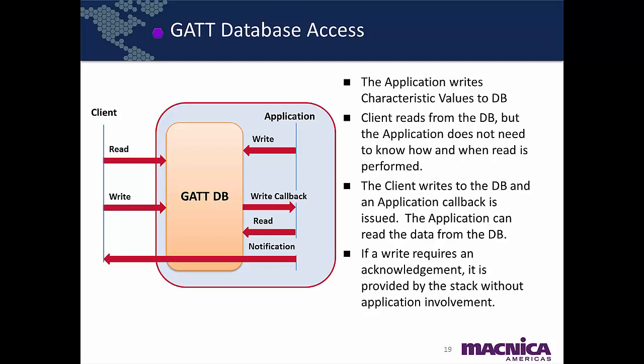At this point, how does the client, let's say a phone application, know that there is a new heart rate value available? Well, a few different methods could be employed. Perhaps the client can be designed in such a way that it just periodically reads the heart rate value from the GATT database on its own terms. Well, this is a brute force way and is not really efficient.